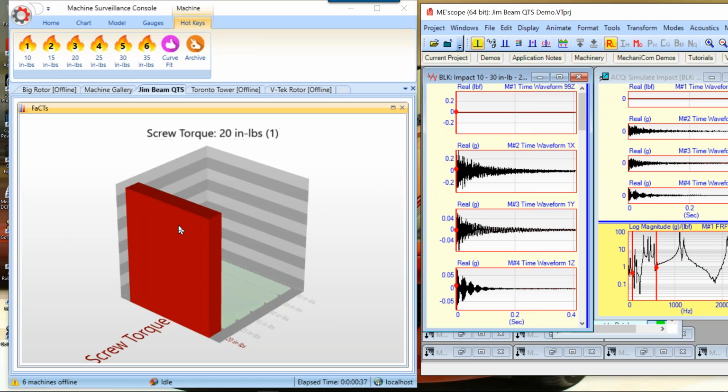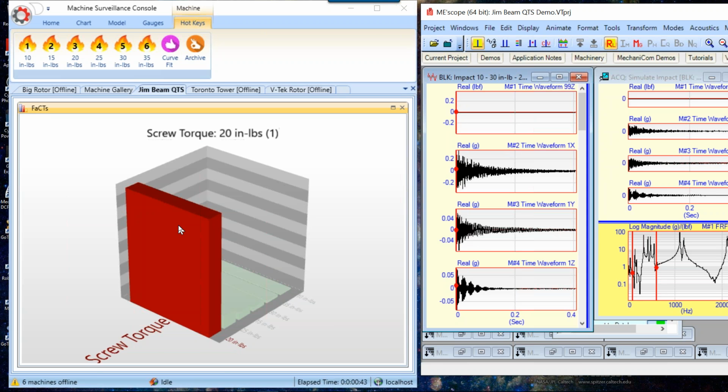So imagine this being used in a production environment where different parts are being assembled with mechanical assembly, bolts and nuts, and various torques. So we can set this up as a go, no-go, where we have in the database the cases, the ODS data of, in this case, frequencies of modes that have been curve fit from impact of the structure itself.